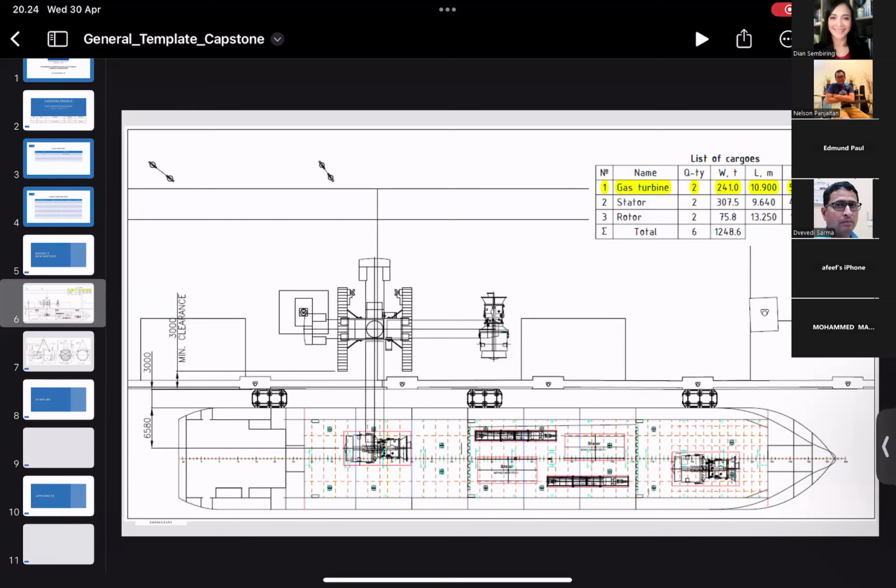So in the capstone project, what exactly would you like to get from this? The UC only, sir? The UC, utilization capacity, based on the crane load chart and the boom length you have chosen, and the radius at which we are going to pick up. Those things only we have to give, right? Correct. Okay, fine.